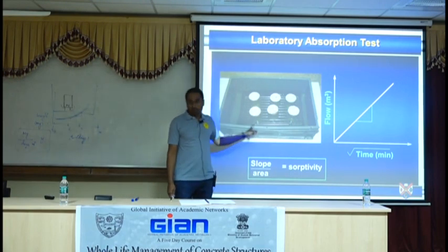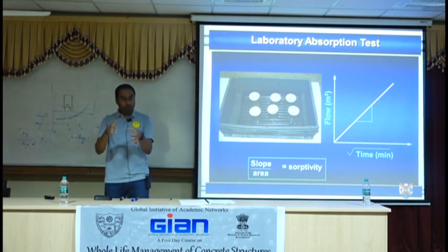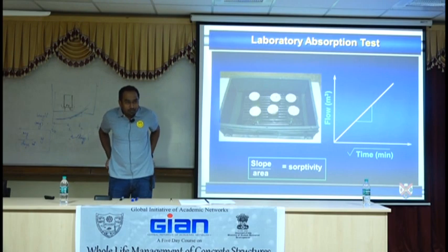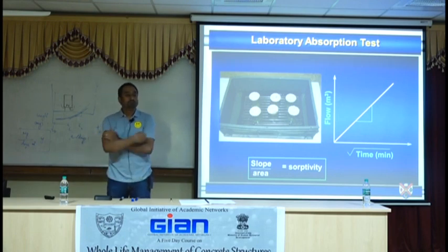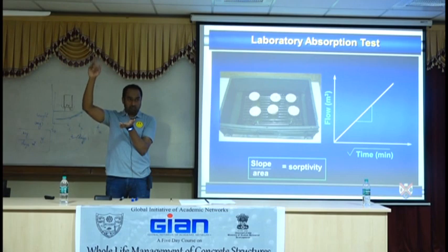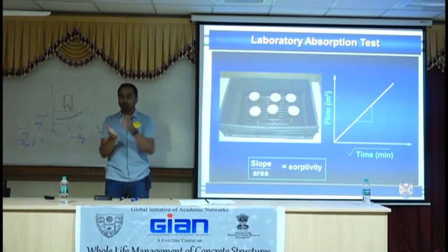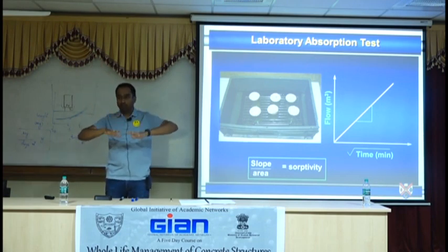This is the cast surface, so they haven't coated. They did not coat the top surface. Why? This is concrete. Capillary rise will be millimeters. When you have water rising up, does it displace anything else? Vapor or water is being displaced. You need to have a space for them to escape. If you don't, it'll stop the capillary. You compress the air for a certain time, and then it'll stop.